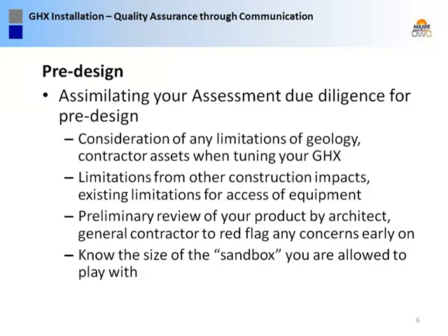Okay, pre-design. Now you're going to take what you've learned through your preliminary assessment of the building loads, the heat pump schedule, where you think the size of your loop field might land, and then consider any limitations of the geology and your contractor assets. You might even have issues with local or state regulatory agencies limiting the size of pipe you can use or the depths you can go to. There are some states here in the U.S. that have those limitations. I don't think that's such an issue in most countries outside the U.S., but our states can be very strange and have different sets of laws.